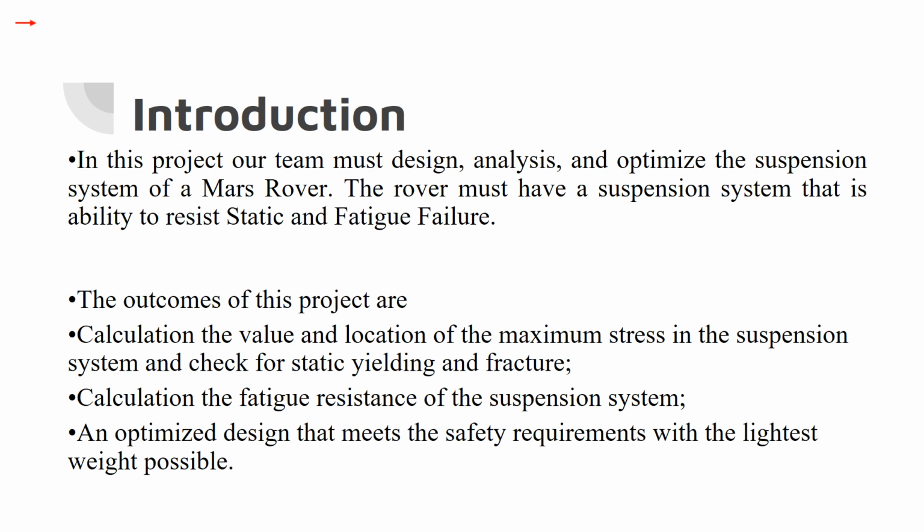Introduction. As I said before, we're designing a suspension system for a Mars Rover, and we're given a factor of safety and must make sure that it's resistant to static and fatigue failure. Some of the things we have to go through are to first find the reaction forces and the location of the maximum stresses in the suspension. Make sure we check for yielding with the initial dimension guess. Afterwards, by obtaining that, we'll be able to optimize the design, make it lighter and as small as possible.